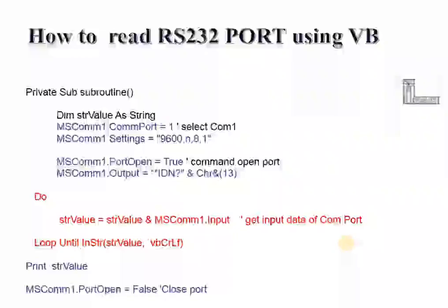Now sometimes you don't have Python. If somebody has Visual Basic, I have purposely given a Visual Basic program to demonstrate the concept more clearly. Here the same thing, whatever you did through Tera Term or Python, is done through VB. You can see you define port COM1, then you ask a question, *IDN?. *IDN? means what is the name of the device. This is usually an RS232 command with most devices.